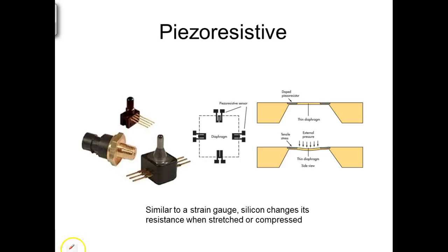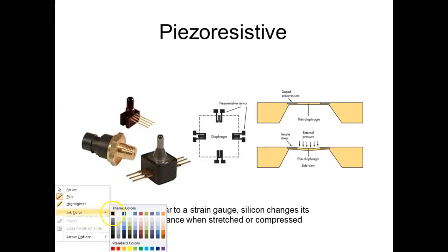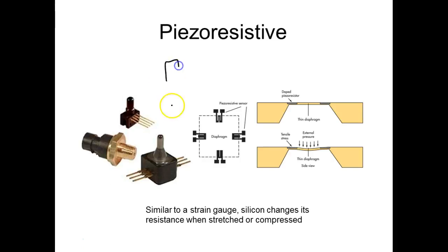But the way the vacuum tube would work is we would have a metal that would emit an electron cloud, and we'd come up here and we'd put a heater in it. And then when you heated that up, it would emit electrons. And then what we'd do on the other side, we'd put something they called a plate, and we'd put a big positive potential there. And what did that do to the electrons? So electrons are negative. You put a big positive potential that causes it to do what?